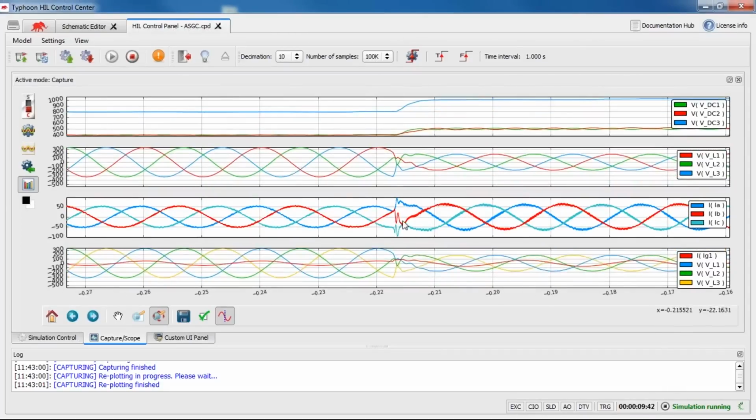As you can see, there is a phase shift there with the goal to actually boost the voltage, as we showed a moment ago, with reactive power present. It actually helps the grid to go back to where it was, and this way the PV inverter is supporting the grid.